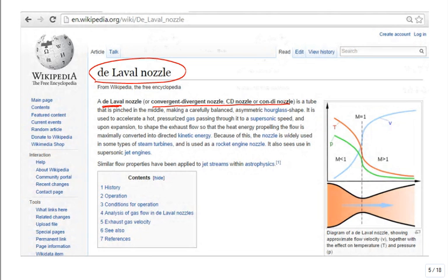But what's interesting about this Wikipedia page is they're starting to talk about not just what the Mach number does. The Mach number goes up until it hits 1 in the throat. And then in the diverging section, it's still a nozzle, and it accelerates and the Mach number becomes greater than 1. True? Or the speed goes up. That's what they're showing here. So the Mach number is less than 1 on this side. It's greater than 1 there. And the Mach number is 1 at the throat.